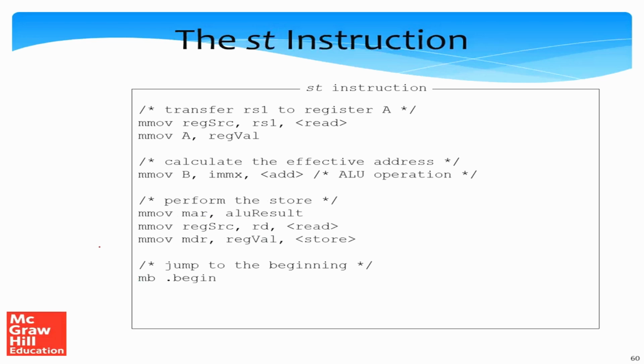Well, we did load, so symmetry says that we have to do store. Store has technically the same format, but recall that in a store a little bit of an exception was made: store does not have a destination, it rather has two sources, and that's fine. One of them is the address source and the other is the data source. This is also a register which contains the data that needs to be stored at the memory address. So we have discussed the store exception.